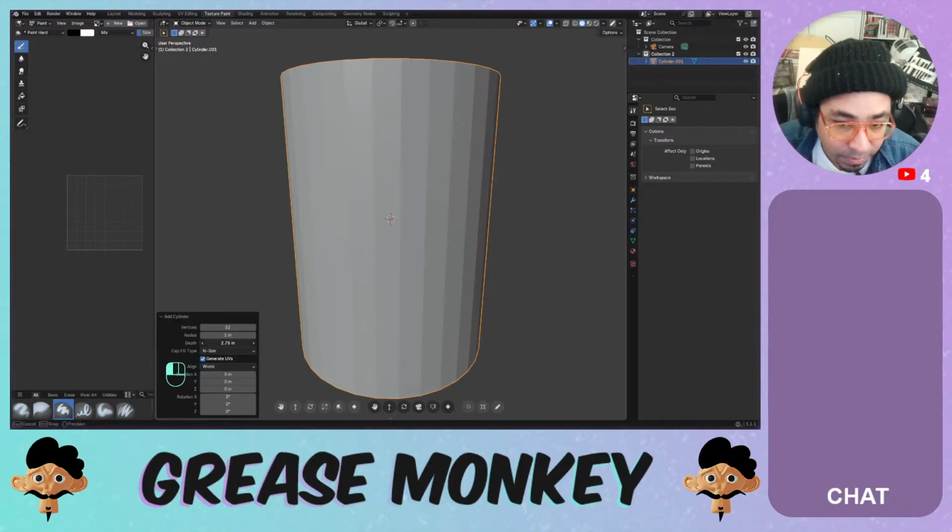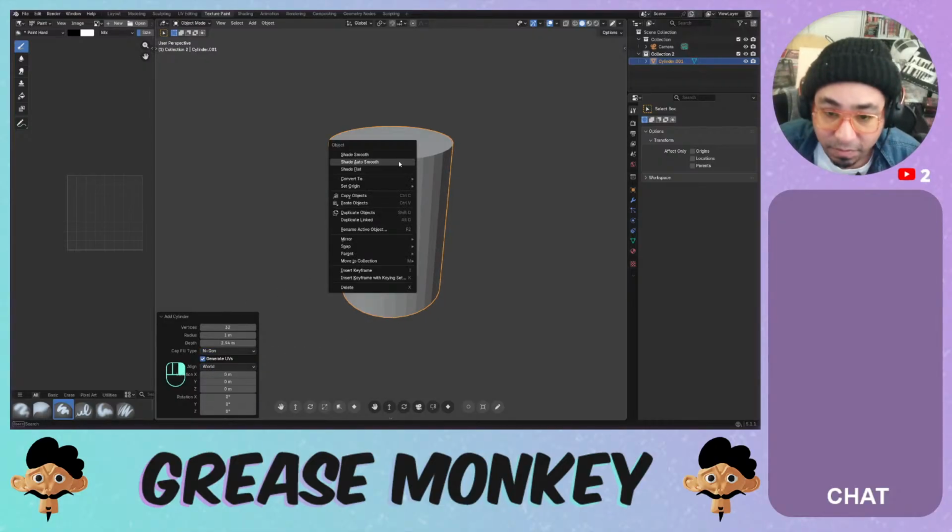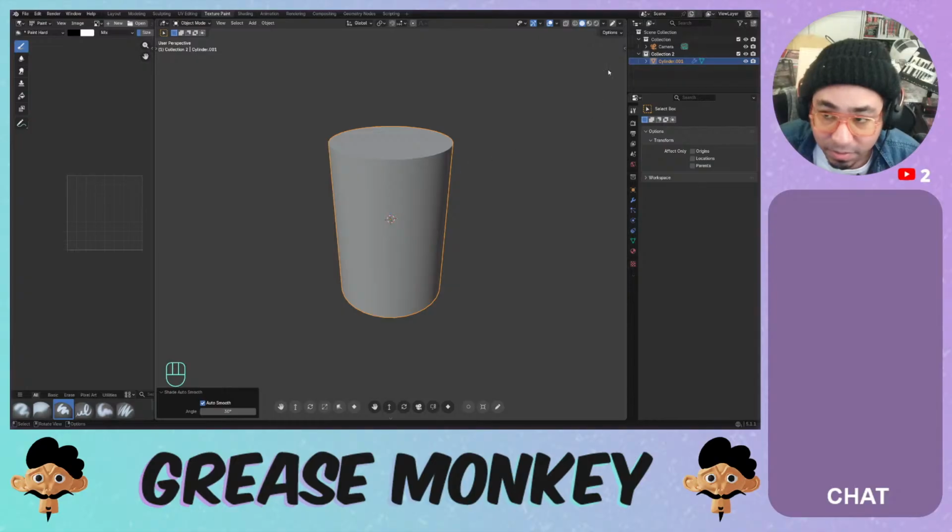We will do a decent size here. Yep, 1 radius, generate UVs. Ngons, we'll do triangle fan. No, we'll do ngon first and then we'll just triangulate it afterwards. So yeah, ngon is good. Ngon, world align, yada yada. Right click that, we'll do auto smooth.